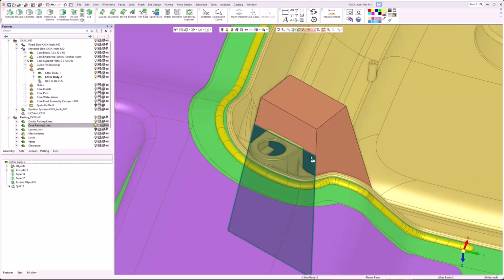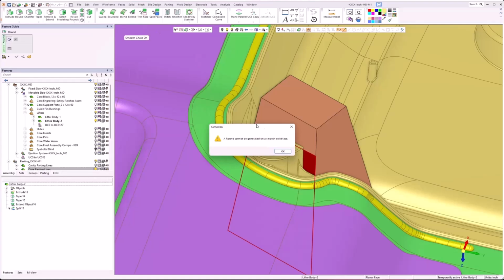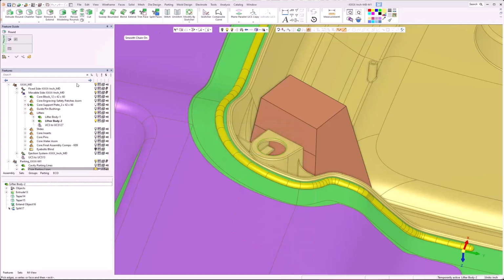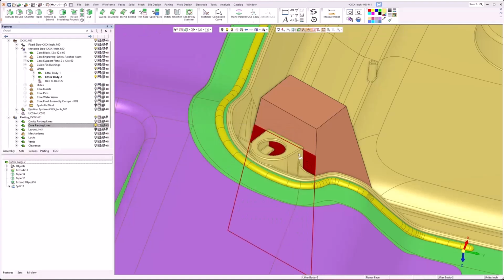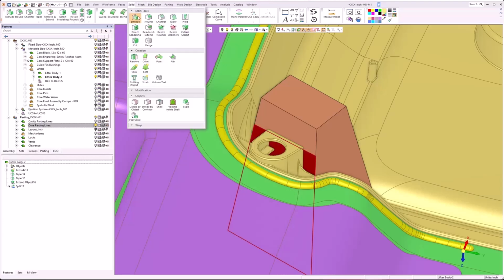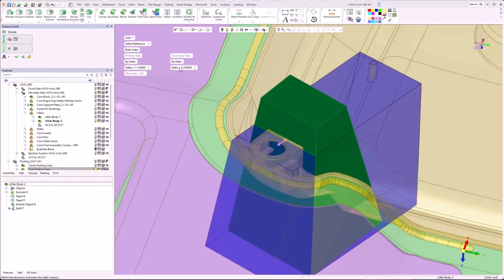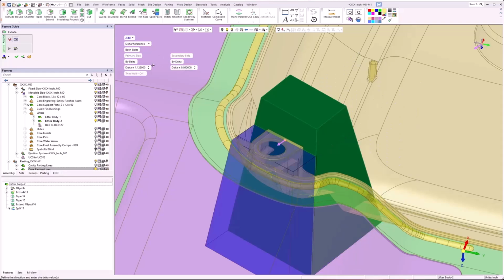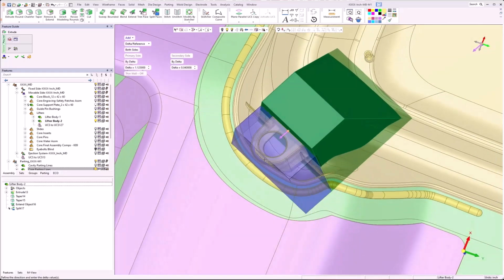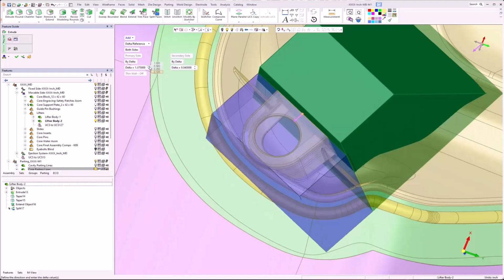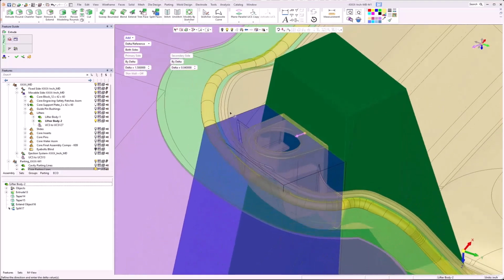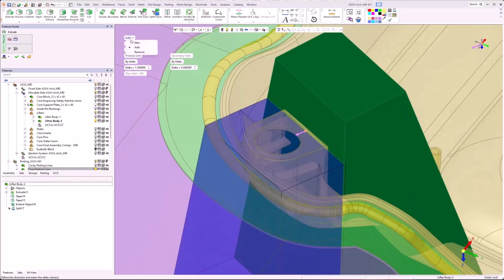And we're going to extrude that face. Oh, not round. Cancel that. I'm going to extrude that face. Make sure we go far enough. That's good. And again, we want it as a new part.